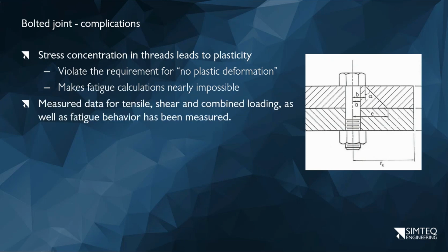So there's measured data, in other words, and different theories and methods that are calibrated to explain the difference in strength due to tensile and shear loading, combined loading, but there's also information related to the fatigue behavior. So that means if I've got the forces on the bolt, I don't care about what happens in the thread. I have enough information if I use one of these theories and methods to calculate whether the bolt